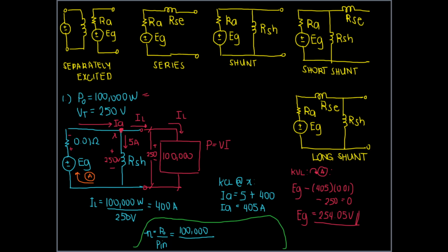There is no way for us to compute the mechanical energy because we do not know the losses here. The losses between the generated EMF and the mechanical power is usually called your stray power loss, which is not given in the problem.